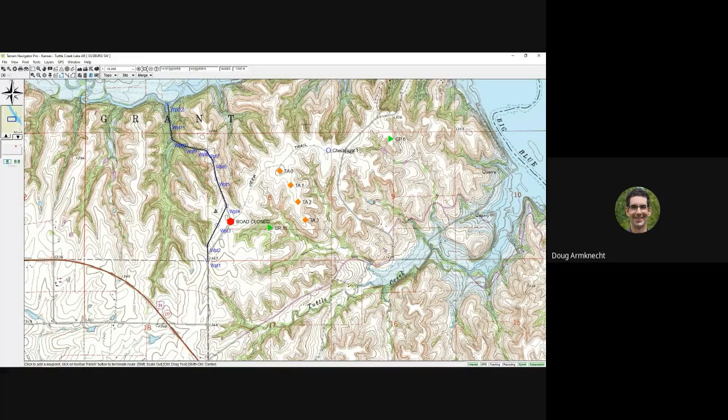You can make basic modifications to the route by moving your mouse cursor over each of these points. So let's say my waypoint here was not quite in the correct location. I'll click it and drag it over here. Or if I want to add to the route and have just a little addition to my route, I just click on any point on the route and that creates a new vertex there.